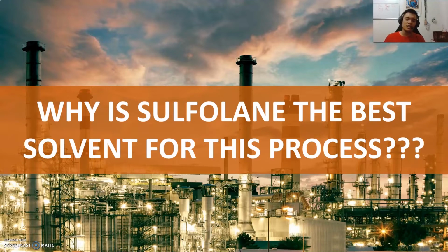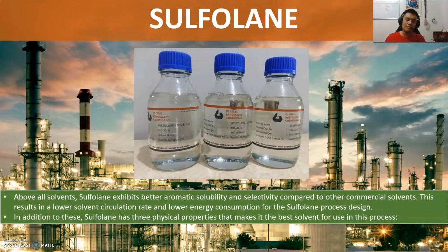But why is it that sulfolane is the best solvent for this process? Well, that's because above all solvents, sulfolane exhibits better aromatic solubility and selectivity compared to other commercial solvents. This results in a lower solvent circulation rate and lower energy consumption for the sulfolane process design.